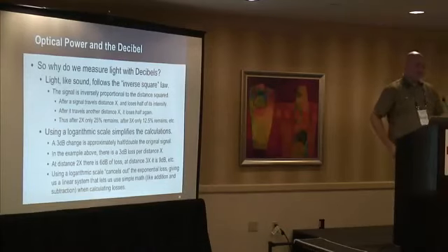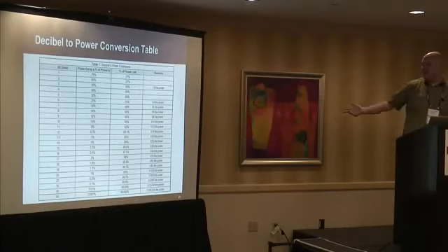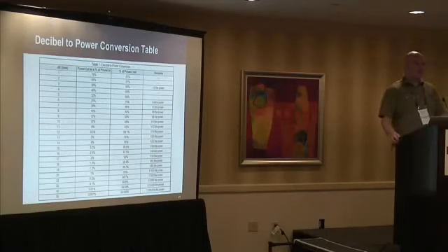So using decibels basically cancels this out. It lets us do simple math when we're working with it. So you can say a 3 dB change every time, and for every unit x, you can say, well, another 3 dB, 3, 6, 9. You don't have to do logarithmic math. That's basically the point. So I threw in a little table that just kind of shows the dB and what it actually is. So you can see you get to what is that, 50 dB, and you get to 1/100,000th of the original power. It doesn't take much towards the end there to have absolutely no signal at all.